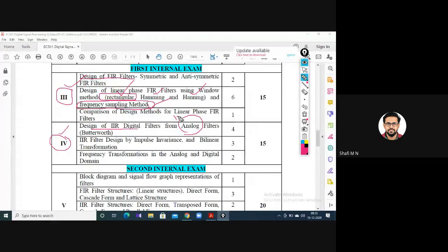now you have to compute your cutoff frequency omega c. We can use two equations: omega p by epsilon raised to 1 by n, or omega s by lambda raised to 1 by n. So if nothing is specifically mentioned, you proceed with omega p by epsilon raised to 1 by n. A point to remember is monotonic in passband. You are familiar with a term like that. Monotonic in passband means your omega p will be equal to omega c. That means your alpha p is actually 3 dB, right? So at that time omega p will be equal to omega c. That is the relevance of the term monotonic in passband.